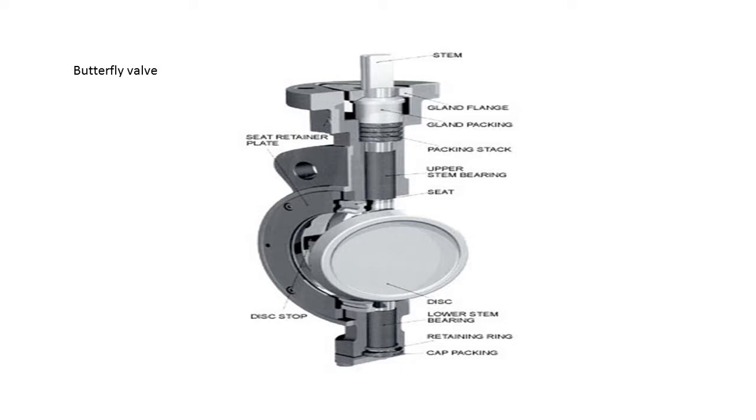Some advantages of a butterfly valve are its compact design, requiring considerably less space compared to other valves. It's very light, and it's quick in operation for either opening or closing. The disadvantage is that the throttling service of the valve is very limited.